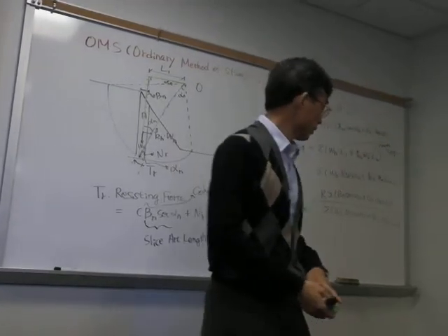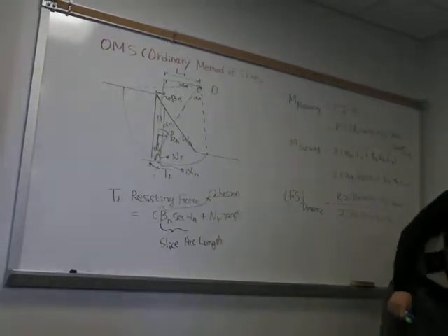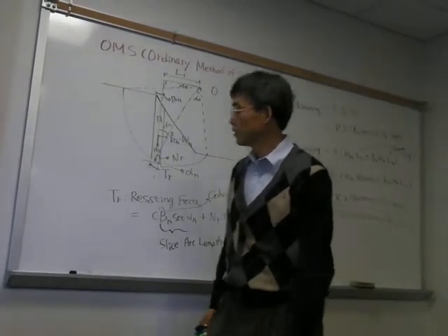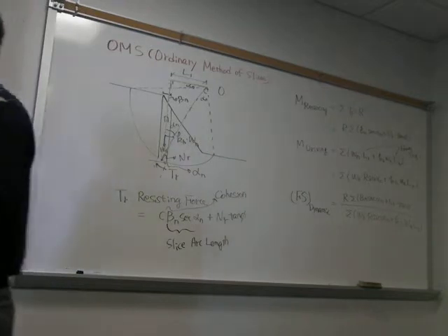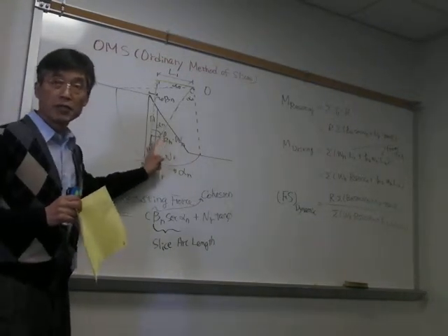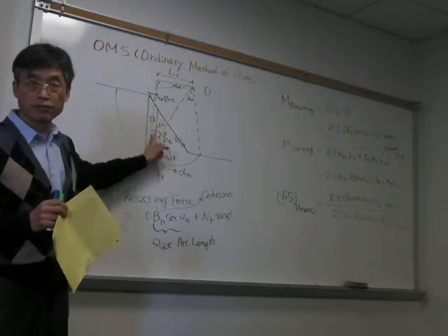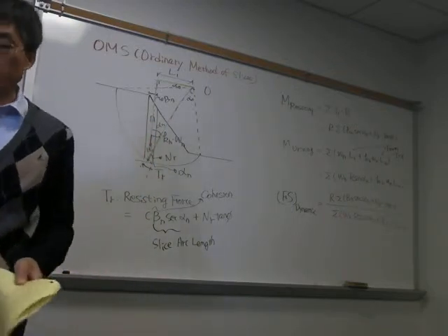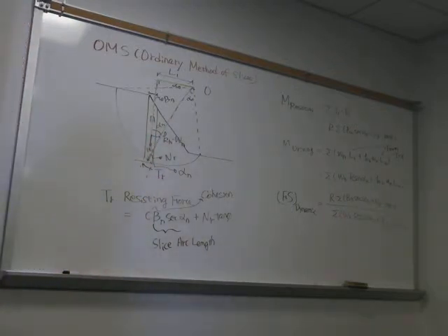That is the factor of safety for dynamic conditions. Of course, if you want to include vertical acceleration, you can include it. But typically, based on my experience, even though we include the vertical acceleration, the difference in factor of safety is not substantial, usually less than 0.1. Maybe that is the reason why people just ignore it.